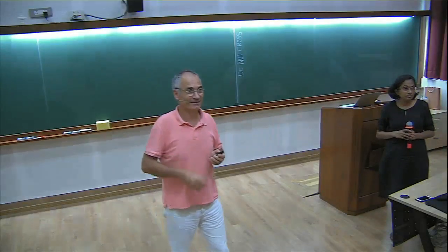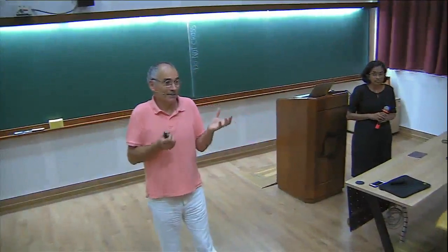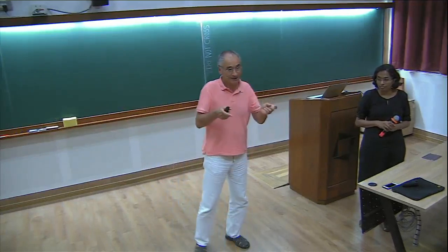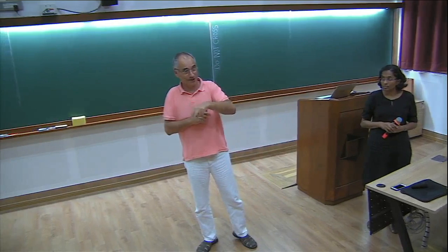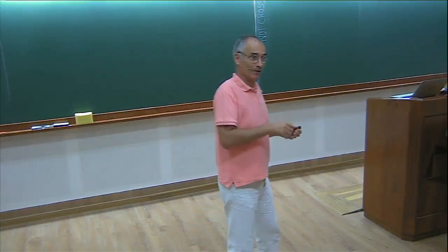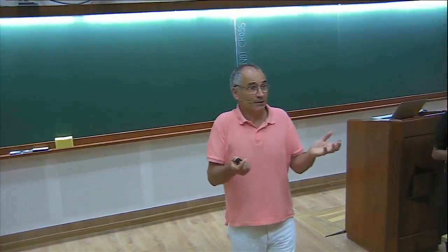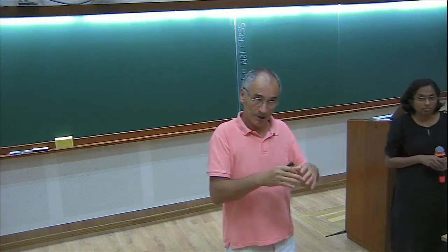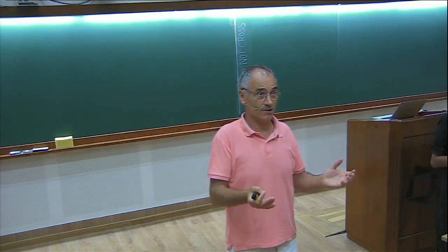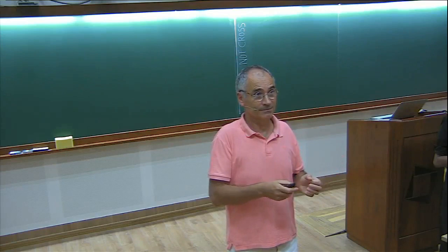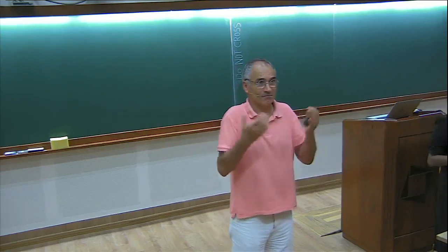Right. No, in the case of, say, bubbles rising. Yeah, but it's the same. It's buoyancy. The case of bubbles is something I've worked a lot on. That was my entrance door to this subject, because I wanted to understand what makes bubbles rise in spiral or in zigzag. That was some 20 years ago. In that case, the bubble is an inertialess body. It has almost no inertia, but it is surrounded by a fluid which has large inertia, and of course it has to adapt to the disturbances the fluid applies to it. So this is exactly the same family of problem, really.